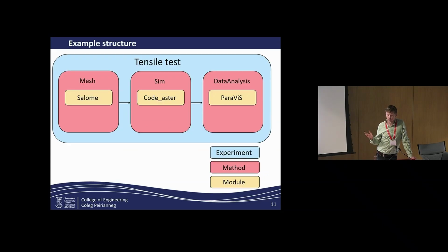For example, the tensile test would look something like this. You have a meshing method, which would use the Salome preprocessor. Simulation will use the Code_Aster FE solver, and then data analysis will use ParaView for visualization or whatever we need to do.